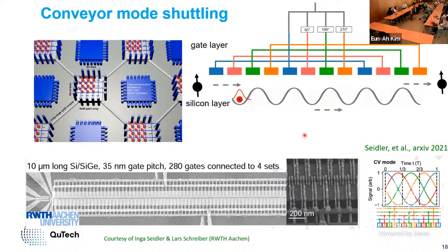Sorry, I have a question about this slide. Sure. Is there an estimate for the fidelity of moving this electron, say, across 10 sites? So yes, there are 2 fidelities here. One is the charge transport fidelity, because when you are moving the charge from left to right, there is a chance you will lose the charge. The charge will be released somewhere. For the charge transport fidelity, we can now achieve many 9s, basically 99 point and many decimals after, so you can basically consider that we can deterministically transport a charge.